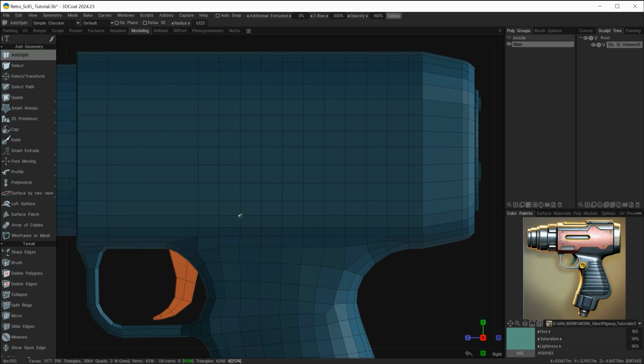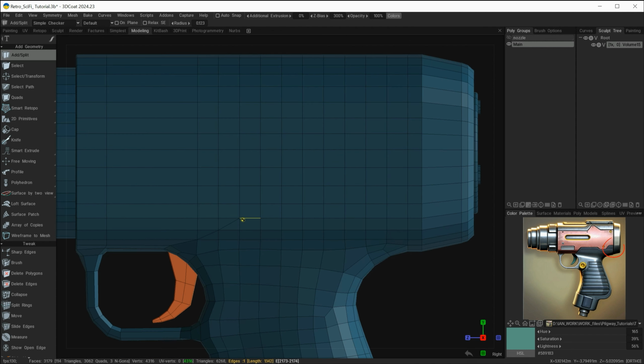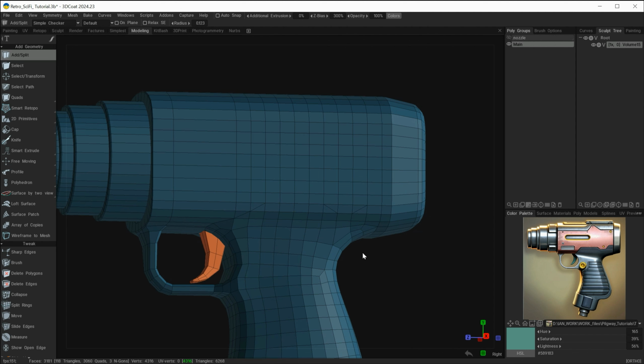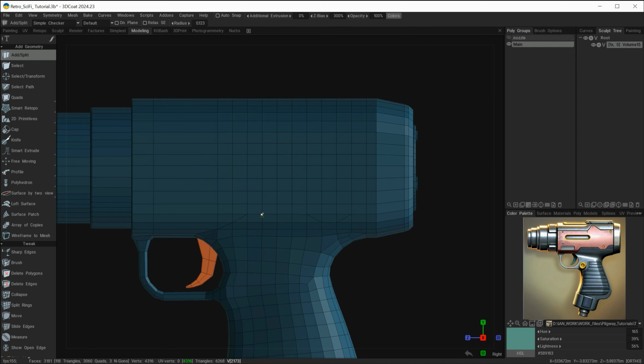So I'm going to choose my Add and Split tool and add some splits to meet with this line and then hit Escape. Similarly, I'm going to move across now to this side. So I'm going to go from here down, Escape, and then add this extra section at the back part here. So I'll miss one edge, move over, and then bring this one back up again, like so. Now with those created, I can go in and start to select and bevel as we did in the previous video. However, we're not quite finished yet.